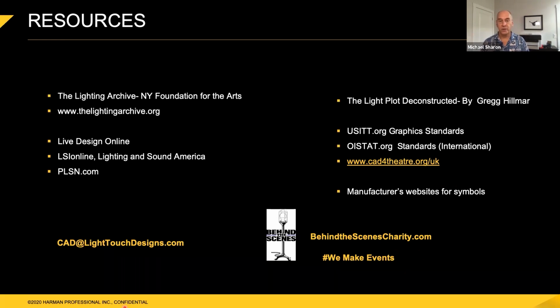And the last thing you want is what happened to us recently: we loaded in a show and realized that the drawings the venue had sent us were the design drawings and not the as-built drawings. All of our rig points were 15 feet off. About 3 hours into load-in, we realized nothing was lining up where it should be, and the venue had sent out the wrong drawings. So whenever you get drawings from somebody else, take it with a grain of salt. You do need to do your own due diligence and check them for accuracy.